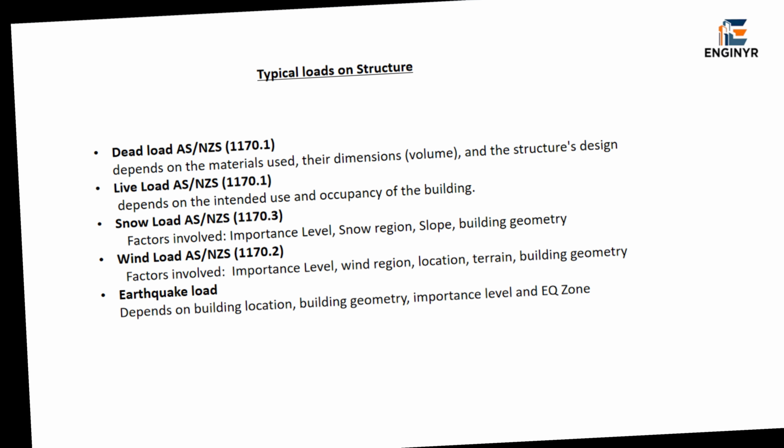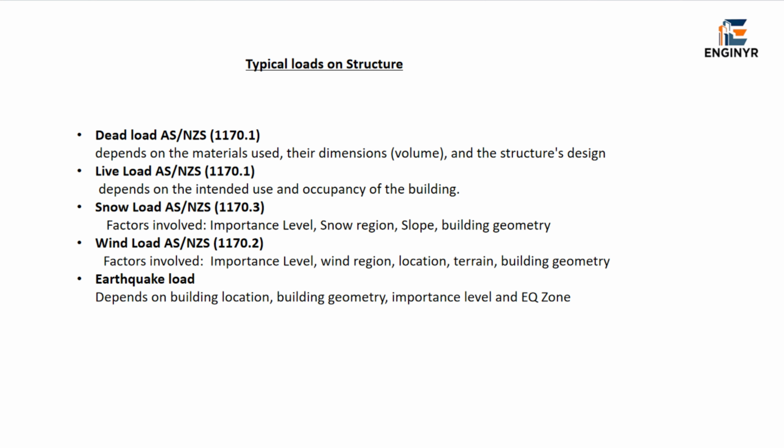Now let's look at the typical loads a portal frame must resist. Dead load, covered under AS/NZS 1170.1, depends on the materials used, their dimensions, and the structure's overall design. Live load, also under 1170.1, depends on the intended use and occupancy of the building.